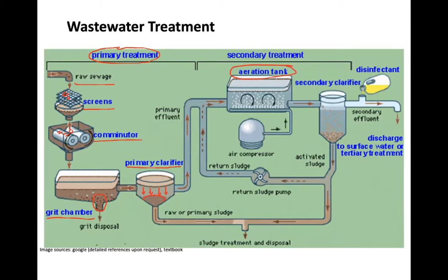But before we introduce water in there, we know that because of the high BOD, there shouldn't be any bacteria inside. And because of that, what we're going to do is introduce some bacteria into the pipe here. Okay, so for example, they can be E. coli or some other benign microorganisms which can consume these organics, let's say consume the BOD, right? So this is the introduction of the bacteria. And inside the aeration tank, we have an air compressor to continuously bubble the air, bubble oxygen into the tank.